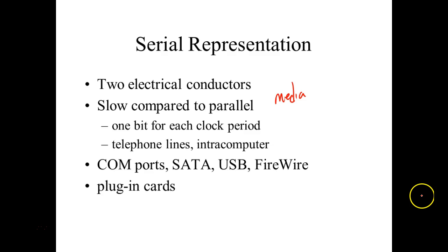Sometimes the fastest method is parallel, which means every bit you send has its own conductor. And then, of course, usually 2 conductors per bit because you've got to have a return, right? So in the old days, on the parallel ATA drive, I would have 32 wires in the cable because it was a 16-bit interface, but for every signal wire we had to have a return. So sometimes we don't have to do that.